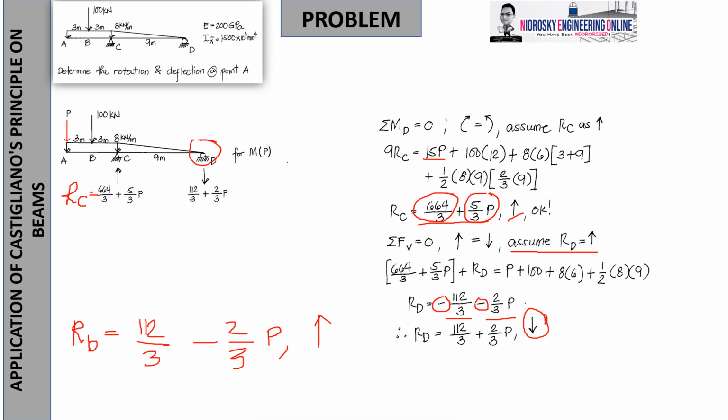So don't worry. Deflection is a function of P. Regardless of whether terms are positive or negative, it's very important that you indicate the proper sign. Because a negative, when countered by a negative, becomes positive, so that also corrects the assumption. So if you get this kind of situation, or perhaps one is negative and the other is positive, then you just stick with your assumption of upward for the meantime. Then later you will be corrected by the true deflection value. And then try to find out, since P and M prime is just a virtual load. Don't forget that. P and M prime, I mean.